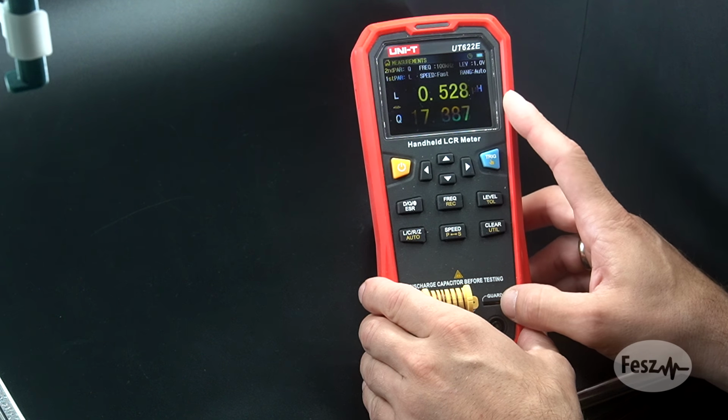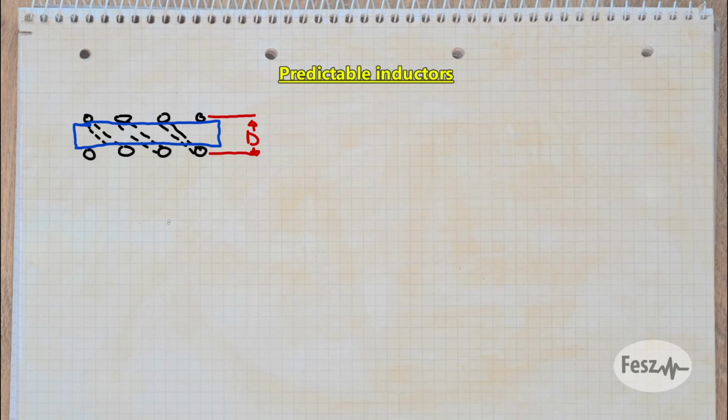Now, there are 3 important things at play here. First, the calculator considers the coil's diameter to be running from one wire center to the other center. If you put your coil on a support, the diameter of the support has to be smaller. Namely, it should be the target diameter minus the wire thickness. And you can also consider a small air gap, since with thick wires, you can end up with the wire not fully touching the support.